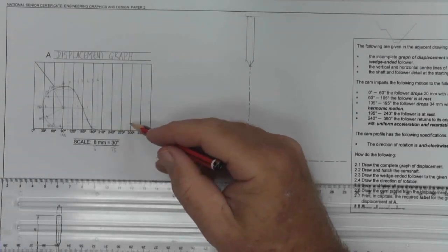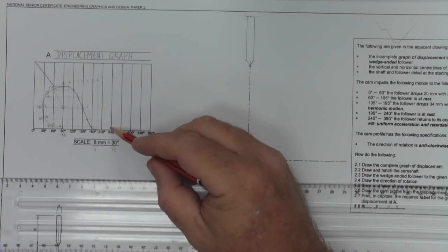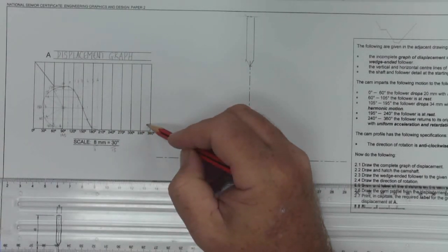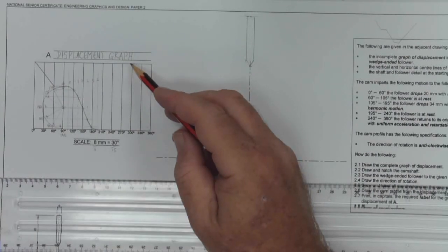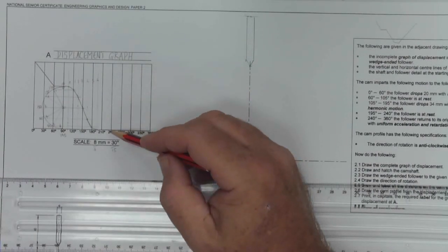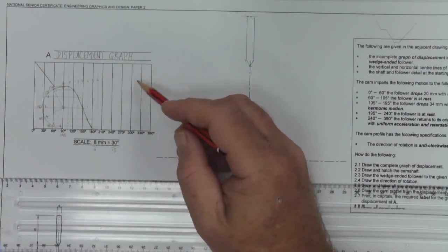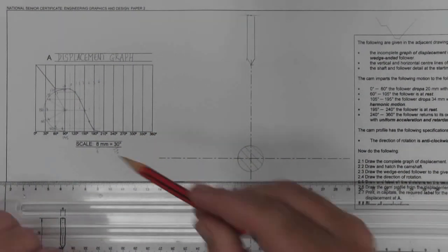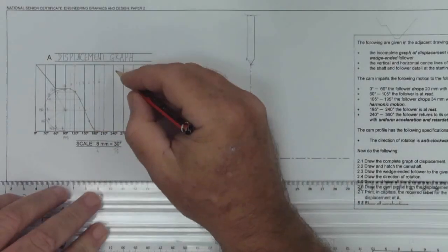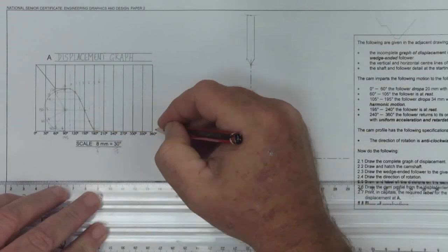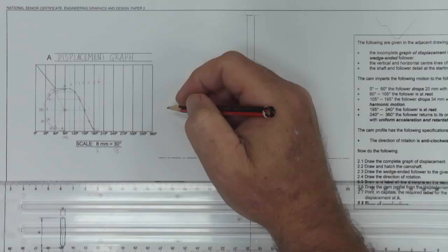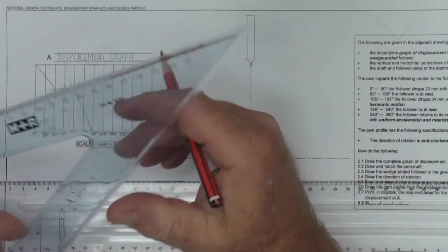Now again, we're trying to find 6 divisions. Now if we check that, so there's 0, 1, 2, 3, 4. Okay, that doesn't work, and that's going to mean we're going to do the line division method just to get 6 points in this little space. As this is going to travel across 4 divisions, what we need to do is have 4 equal vertical divisions. This involves us using the line division method.